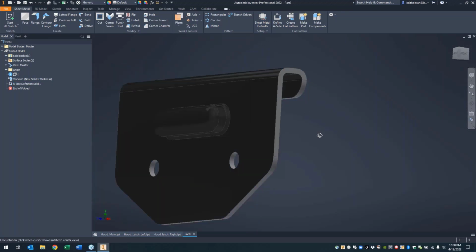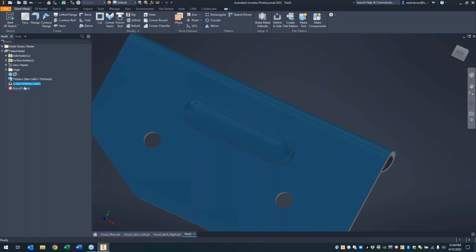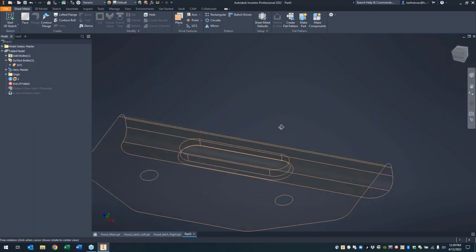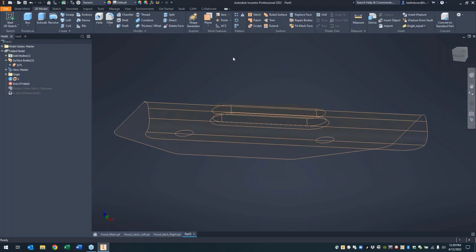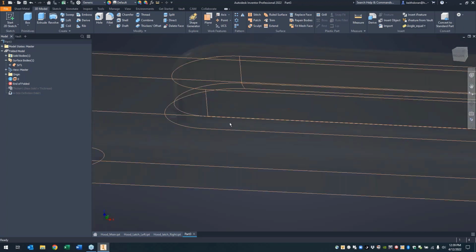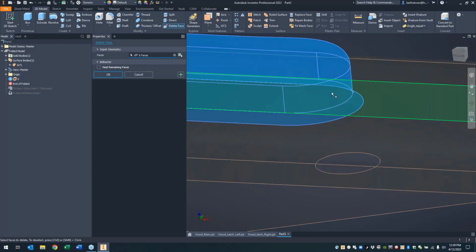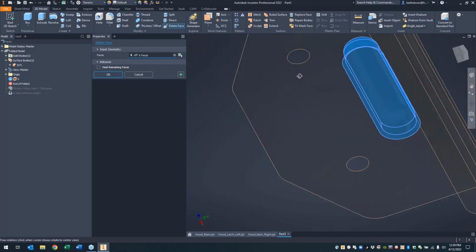Okay, so you know where your bends are. Just trying to use that. All right, so let's do this. We're going to clean up this surface and get rid of that geometry. There's a couple of ways to do this. The first way is we need to remove these facets. In this case, we're just going to use our standard delete face command. And in here, I'm just going to go through and select the half dozen faces that make up that stamped zone.